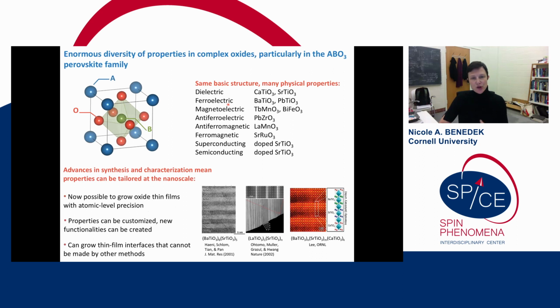All right, so the family of materials that we spend most of our time working on are Perovskites, a pretty well-known family of complex materials. This is known as the cubic Perovskite structure. It's often taken as the sort of archetype or the prototype for this family. So Perovskites have a cation on the A site, a different cation, typically a transition metal, on the B site, and that's octahedrally coordinated by anions, usually oxygen.